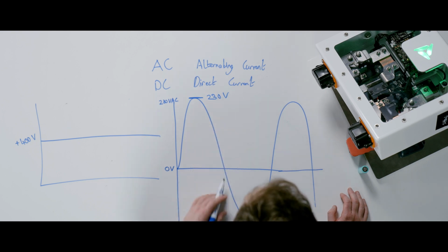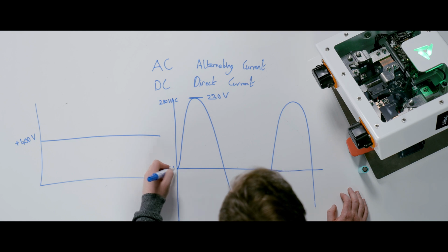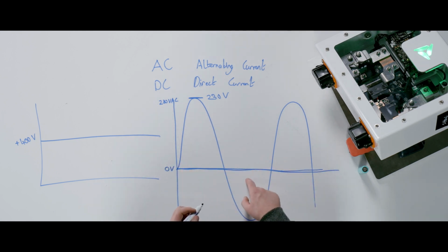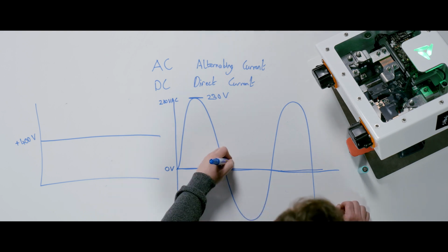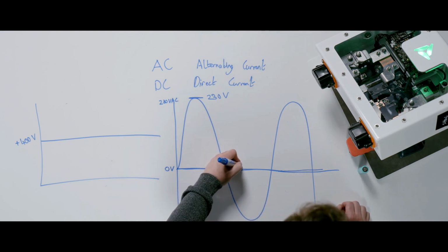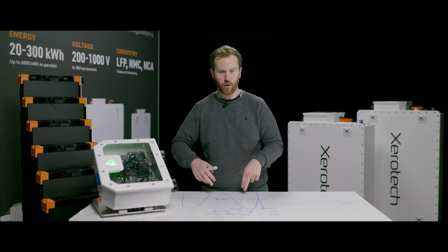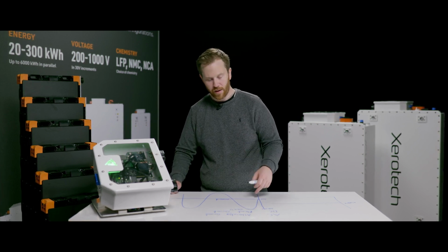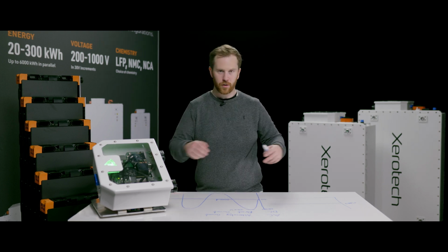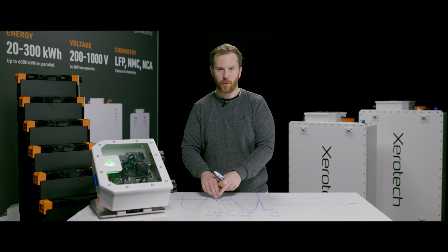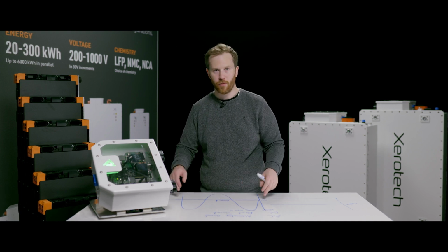So that's 230 volts with respect to this horizontal line. We have to define what that horizontal line is, and that's what many people will call ground. So if we say it's the ground, it's literally the ground. So in power stations, they reference the power to ground. They drive large, big metal stakes into the ground to provide something called an earth reference or a ground reference.